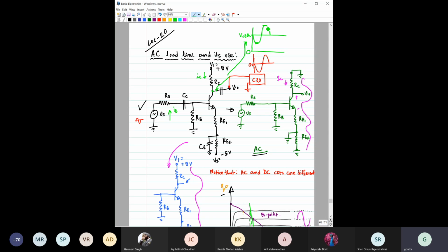And obviously from the sinusoidal signal, you should be able to measure the amplitude of the signal. At the same time, you can also measure the time division. So from this time division, you should also be able to find the frequency of the signal. After today's class, I will post one video